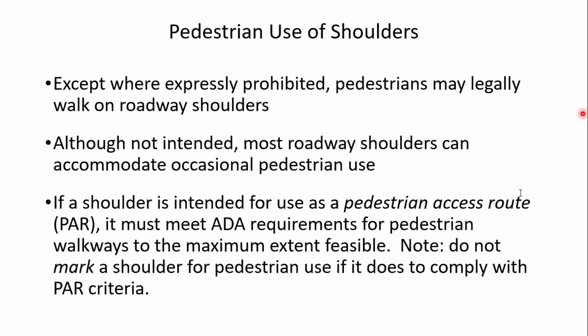James says, seems like we're also wasting the space by not giving car drivers that auditory feedback until they get to the very edge of the pavement. Yeah, I would agree with that, although as that FHWA research found, at least on 2-lane rural roadways, it really doesn't matter where the rumble strip is placed on the shoulder, which I found to be interesting. And Doug says, gives more recovery room for drivers. Yeah, exactly. So I appreciate those comments.